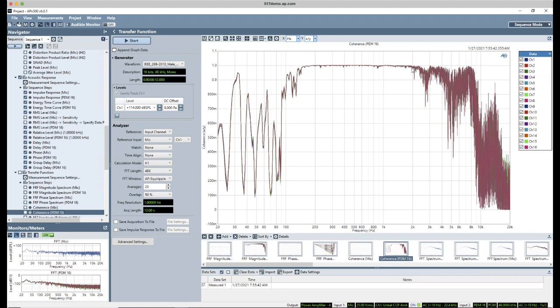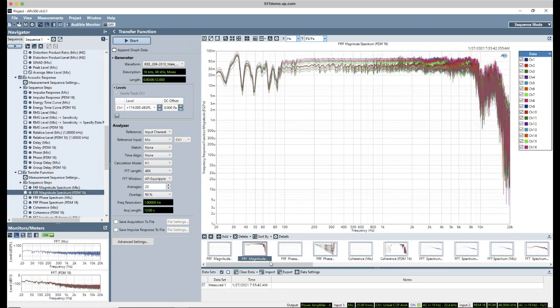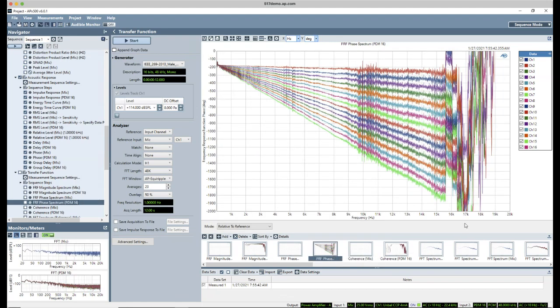And what you can see here is that the coherence of this test signal is pretty well defined. We have good coherence above, say, 150 hertz, and it gets somewhat noisy, but then really falls off like a brick above 8 kilohertz. And so we need to keep that in mind when we look at all our measurement results. So everything from the frequency response to the phase response, I'll say, is a bit janky when we're outside the range in which our test signal had energy.